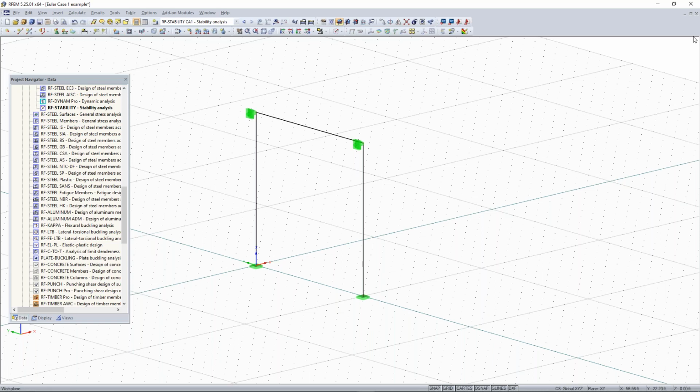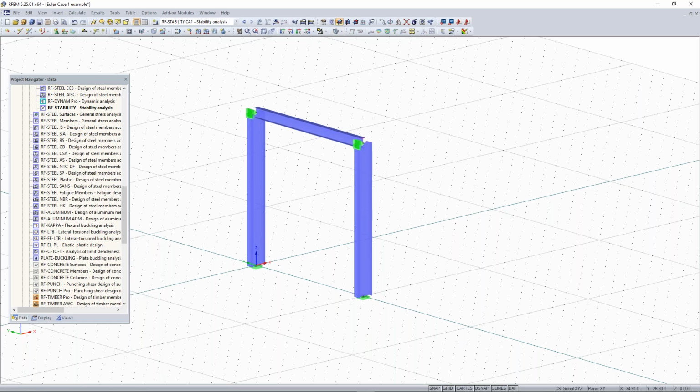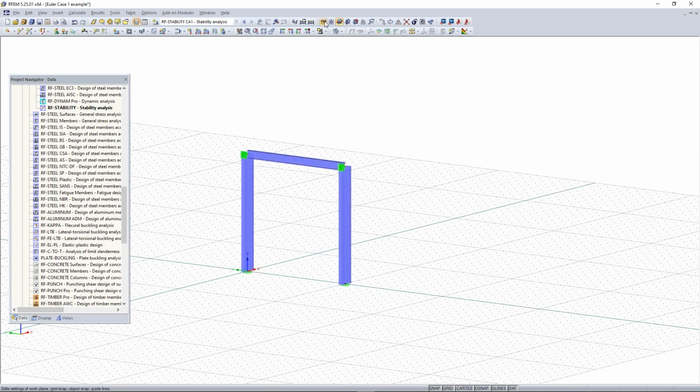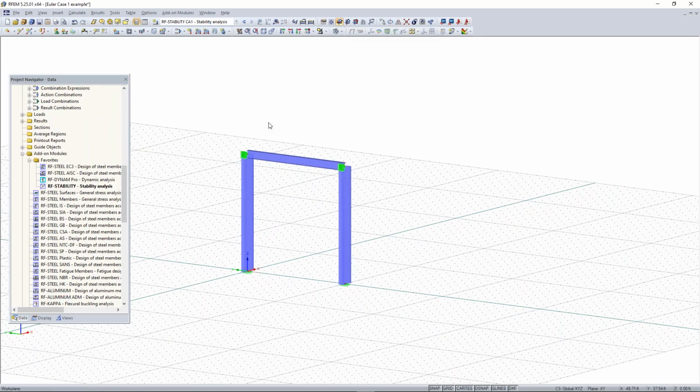The final question that I see here is if we use two members as one metal column, like a built-up column, can we use RF-STABILITY the same way? So Alex, basically, I can quickly explain it. I think the question is asking if you have two members that are modeled separately but form one continuous column in what will actually be constructed out in the field, RF-STABILITY will behave the same way. It maybe doesn't necessarily change the mode shape depending on if the member is broken into two separate segments. So hopefully that answers the question.